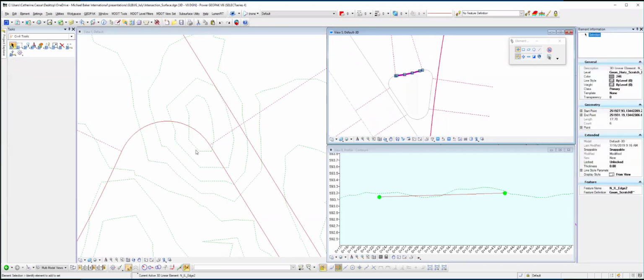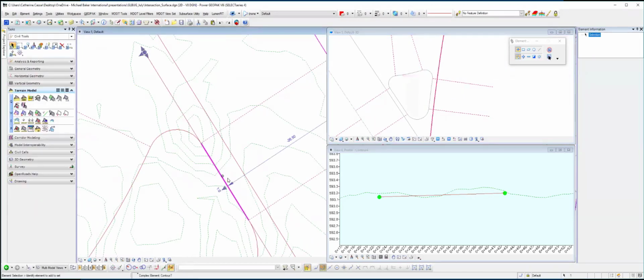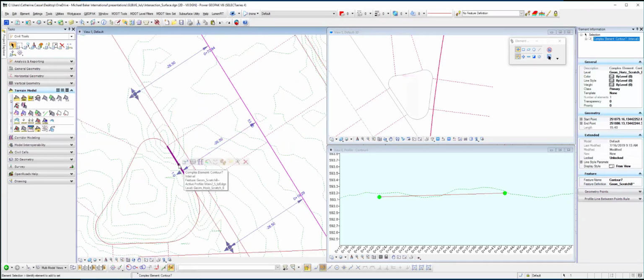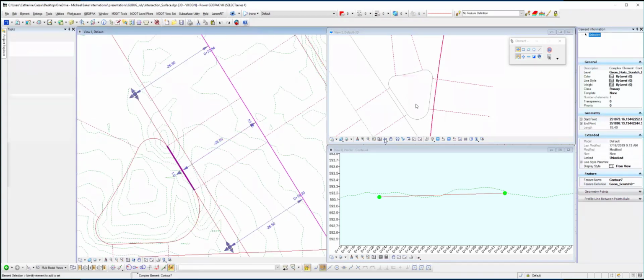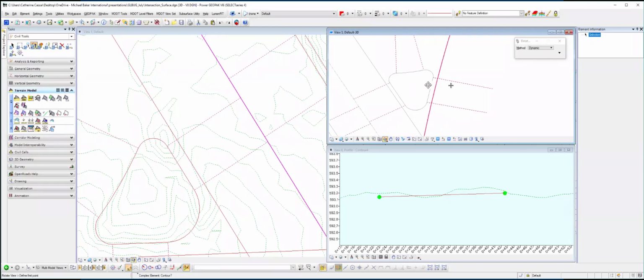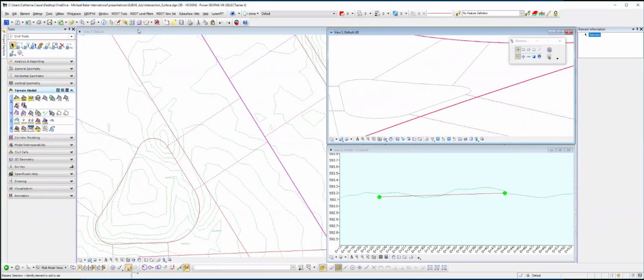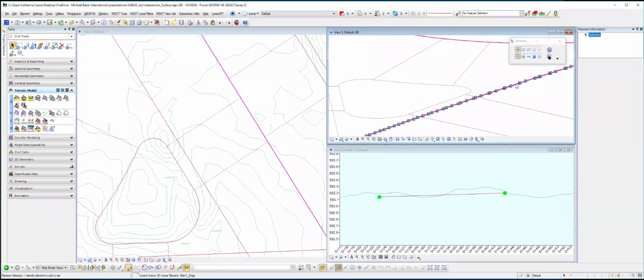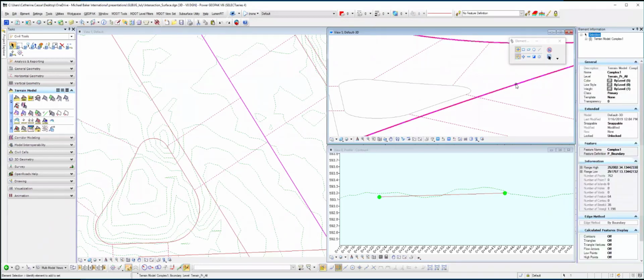If your feature length itself is shorter than the stroking distance, that can cause you to have not enough points in there as well, and you'll have some inconsistencies in that overall surface model if you don't take that into account. So there's just some fine-tuning to consider.